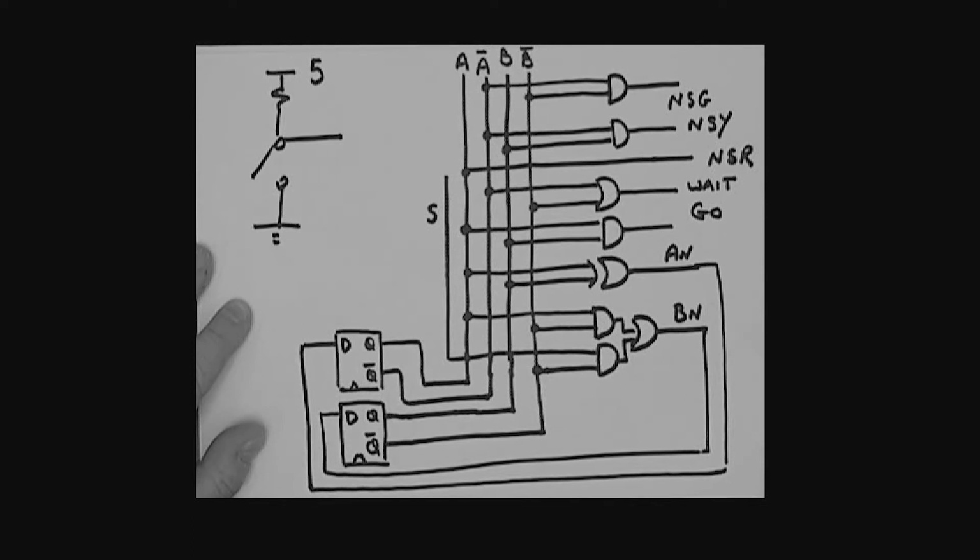And so if I'm not pressing the switch, it would be a 1. That's not what I want. I want a situation where when I press the switch, S would be a 1. That is consistent then with our state diagram, okay? Remember, when S is a 1, that's what causes me to change states on the next clock edge.